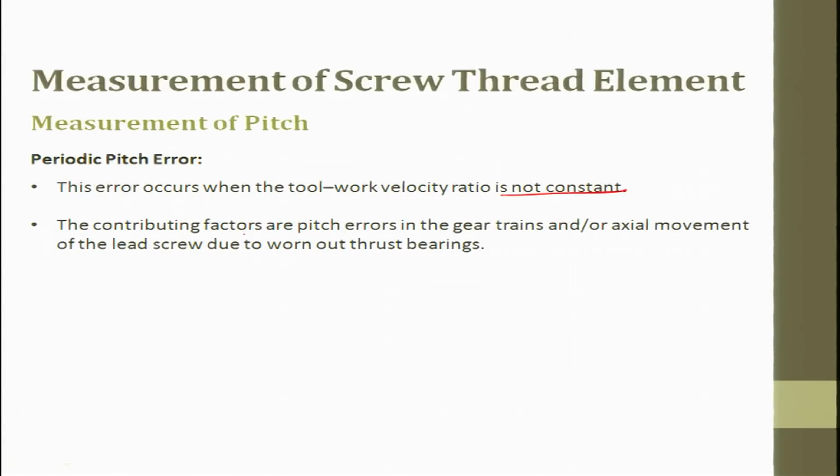The contributing factors are pitch error in the gear train and or axial movement of the lead screw due to worn out thrust bearings. We always will have periodic pitch error.